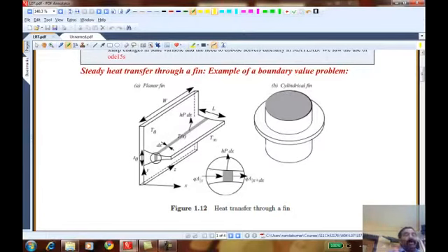you will find surfaces like that, fins, that increase the heat transfer surface area and so increase the heat transfer rate. If you open up the front of a car, you will see a radiator, and that has some fins too. As you pass air through that, it takes away the heat generated in the engine.